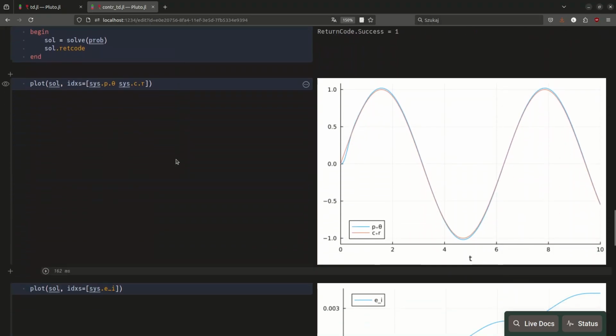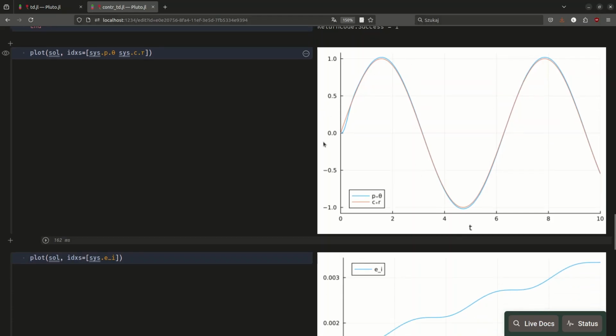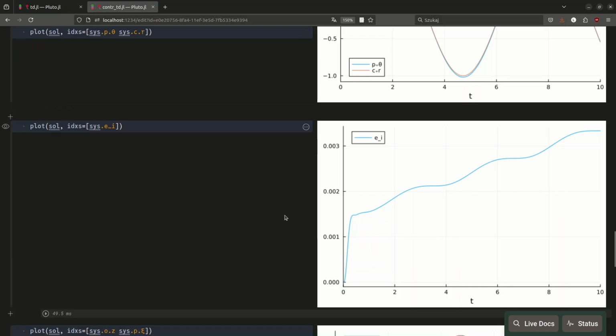And when we check the simulation outputs, we can see that we are still quite good, but worse, which is clearly visible on this plot, which looks the same as before, but if you check the scale, the integrated error is like 3 times bigger than it was in the case when we knew exactly the derivative of the reference, which is, I think, expected because we saw some delay in the tracking of the derivative in the case of TD alone.